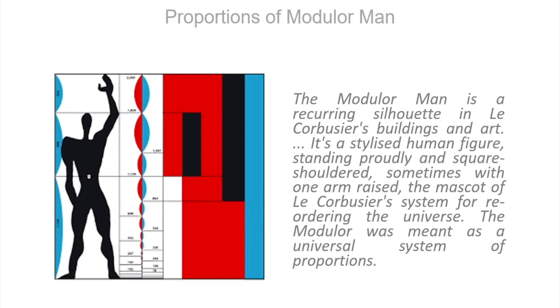So before you start to sketch out your ideas for furniture, get your measuring tape out, and I want you to measure a few things. Measure the seat height of your chair to the floor. Measure the tabletop height to the floor. Measure a dimension of the floor to the top or the opening of a door jamb. And then if you have anywhere in your home or office that is a stand-up countertop height, I want you to take a measurement of that. So note those 4 measurements for yourself.